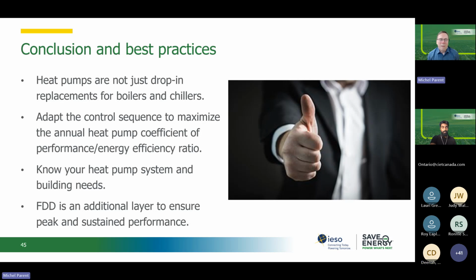So I'm going to take a wild guess here, because the weight question that you raise is usually not a problem because, like I said, a heat pump is just an air conditioner, and if you had a 10-ton and you replaced it by a 10-ton, the weight difference should be very little. And the duct size usually, and not usually, all the time, ducts are sized for cooling purposes. So is it possible that they upsized those units, let's say from 10 ton to 15 or 20 tons, and that explains both the duct size issue and the weight issue? Because duct size is usually not a problem when you go from gas to heat pump, because the duct is sized for cooling, so it's way sufficient for heating, even for a heat pump.